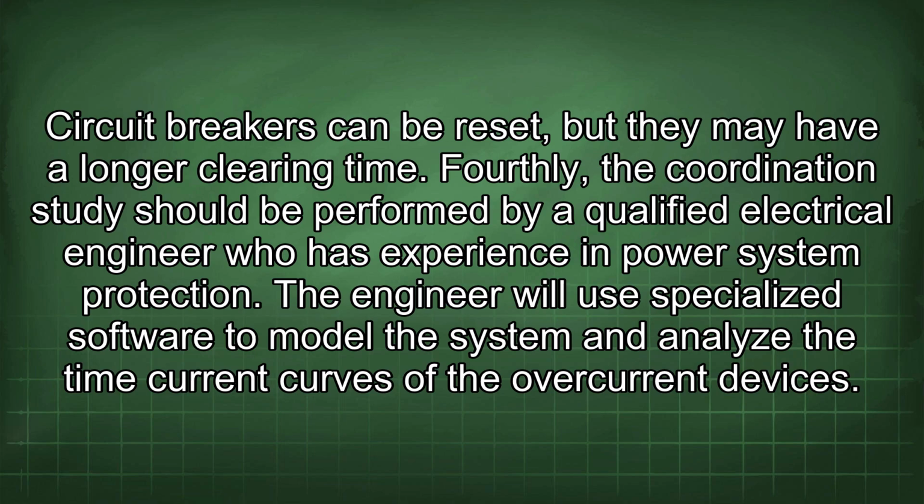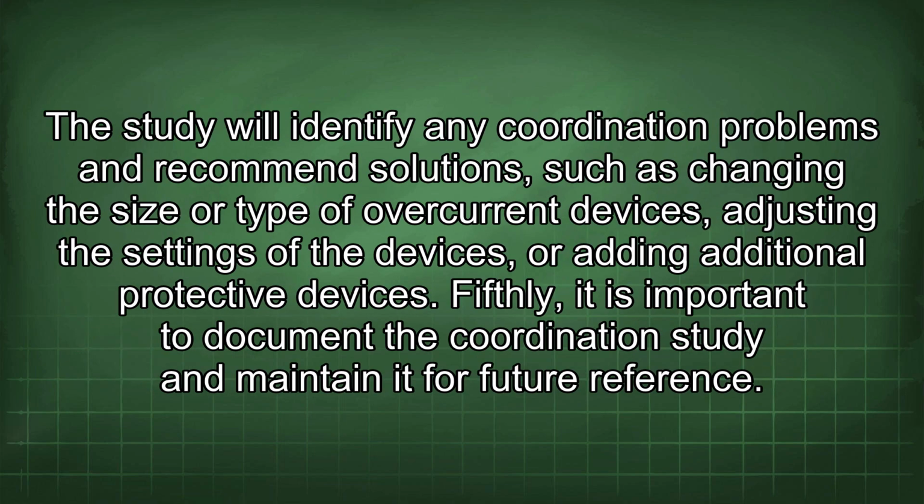Fourthly, a coordination study should be performed by a qualified electrical engineer who has experience in power system protection. The engineer will use specialized software to model the system and analyze the time current curves of the overcurrent devices. The study will identify any coordination problems and recommend solutions such as changing the size or type of overcurrent devices, adjusting the settings of the devices, or adding additional protective devices.